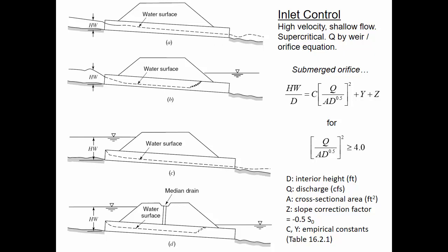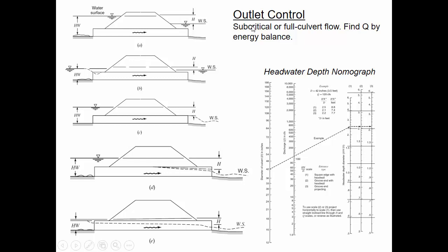And the most common thing for us to do is to put the culvert down so that the bottom of the culvert matches up with the original channel. The bottom of the culvert is called the invert, and so the most common thing is just to put the culvert invert matching up with the bottom of the original channel that was there to begin with. So that's inlet control. In outlet control, you have relatively shallow slopes. And so the pipe isn't at the same slope because the stream was kind of a slow-moving stream. And so subcritical conditions, meaning that the water velocity is low. So that's usually what happens when you've got outlet control.